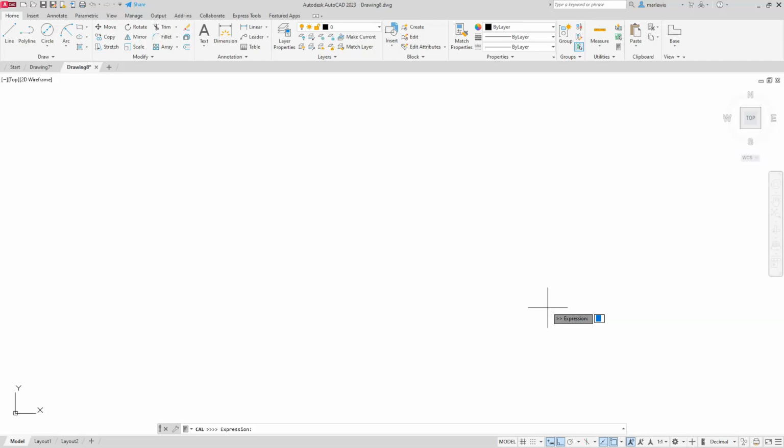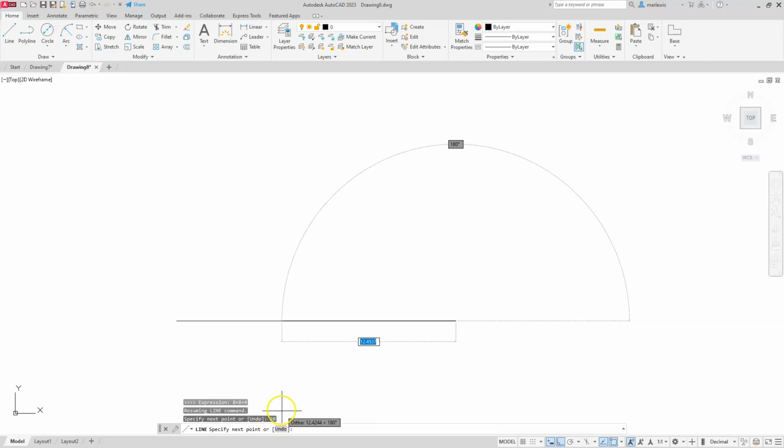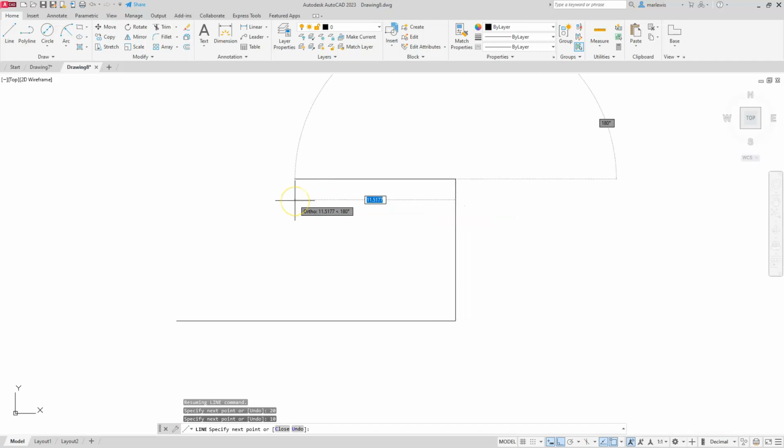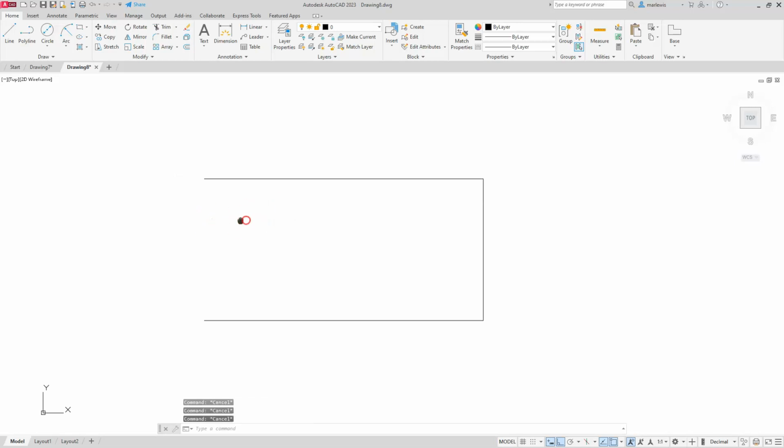And I'm just going to type this in just like I would a calculator. I'll go 8 plus 8 plus 4. And once I hit enter, it's going to do the math for me. If you look on my command line right where I'm at, it says that number is 20, which is the number that we came up with in our head, or when we calculated it on the PowerPoint. So go up. Let's type in 10. Let's go back to the left. Let's type in 20. And for what we know right now, we'll go ahead and stop right here. Go ahead and hit escape.